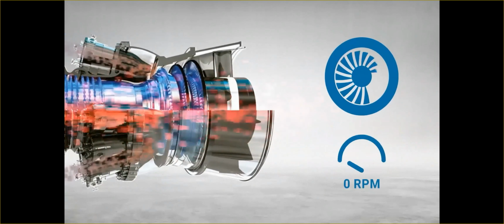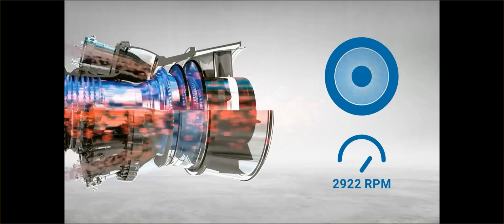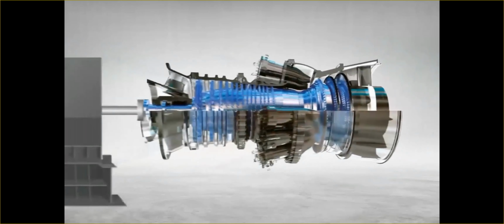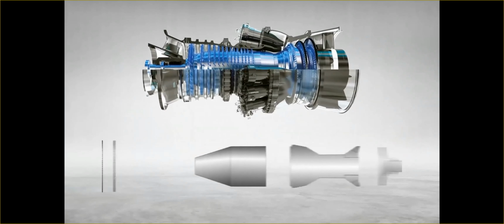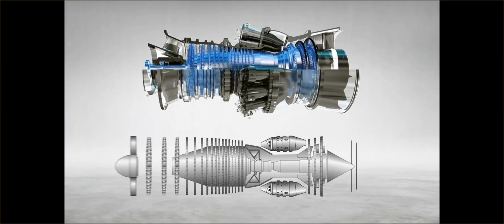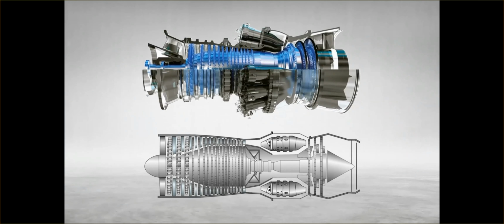This extremely hot and pressurized gas will go through the turbine blades and will cause the turbine's shaft to rotate to more than 3,000 RPM. This energy will go from the shaft to a generator to produce electricity. The gas turbine is exactly like a plane's jet engine, with one difference: a gas turbine used in power generation has large blade rows in the turbine part to convert the hot gas flow to rotational power in its drive shaft to run a generator. But an airplane engine ejects most of the hot gas to create thrust.